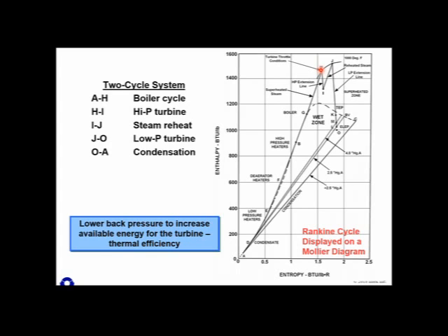It's a vapor state, and we're going to use up some of that potential energy by expanding that gas through the turbine, converting that stored potential energy into kinetic energy and extracting work with the turbine. So the enthalpy in that steam decreases as it's driven through the turbine, and we're extracting work, creating electricity. And then in this simple Rankine cycle diagram, we're going to put that steam back through the boiler as reheat steam, and then drive that steam through an LP turbine.